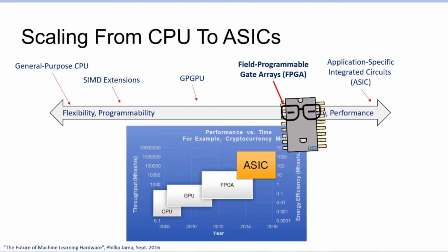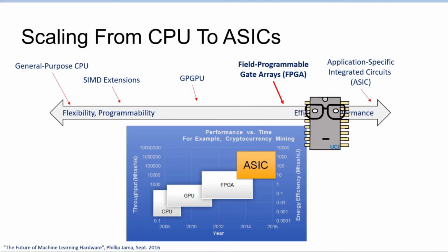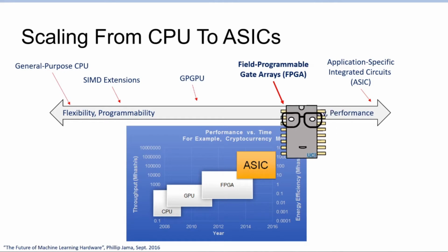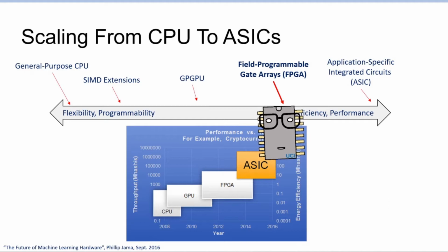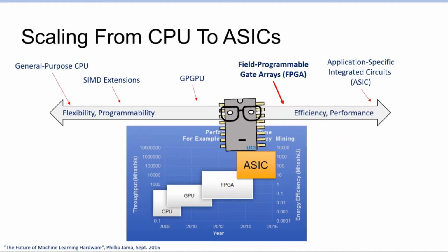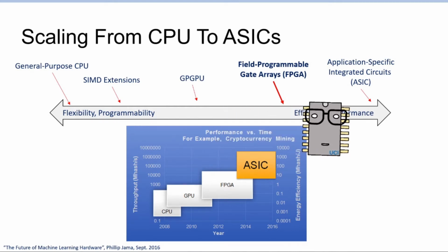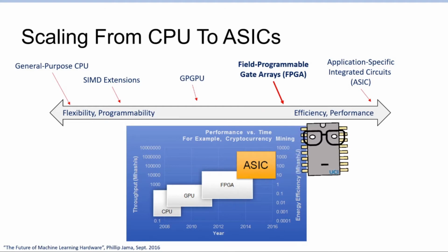At a very high level, it tries to have the efficient, programmable, dedicated circuit aspects of ASICs, but still packaged within a relatively easy to program abstraction. So you can see from this position here, FPGAs are probably less efficient than ASICs, more efficient than GPUs, but more difficult to program than GPUs and easier to program than ASICs. And we'll get into details about what exactly FPGAs are, how they're programmed, and why it's difficult or easy, etc., in the next couple of slides.